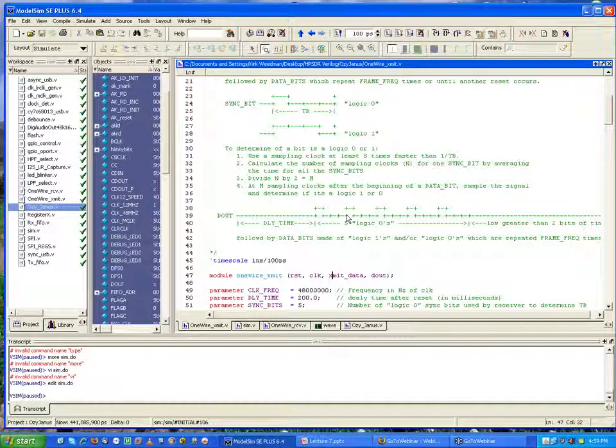Let's say 300, it counts. And then it does it for the next one. Say that one's 301, and another 300, and then another 300. And then you could, at the end of this, if you get this long stretch, you can say, oh, I got sync bits. So I'm going to take my average of those 4, and that's going to be the amount of time between rising edges that I'm going to use for collecting data. Okay, so let's say it turned out to be 300, your average.